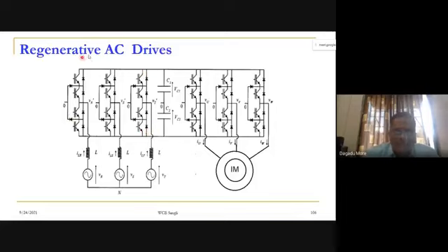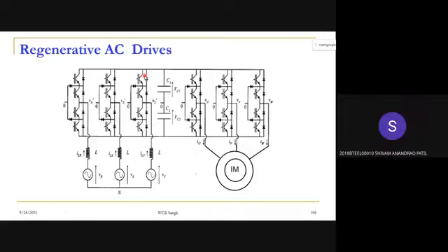Okay. So what is the benefit of this 3-level diode clamped multi-level rectifier? What is the advantage of this scheme? From the supply point of view, what is the advantage of the PWM rectifier? We have spent 10 lectures on the PWM rectifier. So what is the advantage? Source current is sinusoidal. Okay, one advantage, correct.